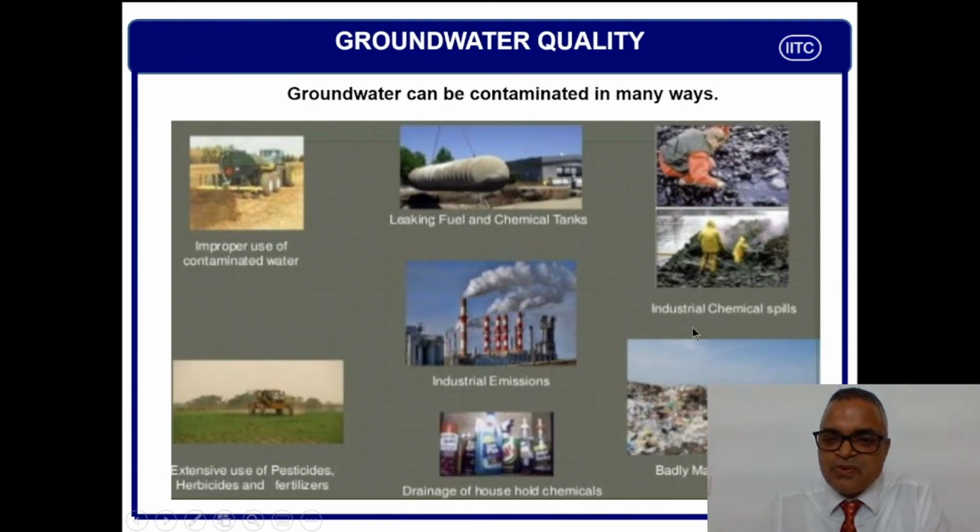My friend, be careful. Badly managed landfill. You see, we see bigger and bigger heaps in the landfill. We feel this is very good, very safe. But guys, these are very poorly managed landfills. Probably it does not have an impervious layer. All the toxic water leachate will go inside the ground. It will go in the aquifer. It will contaminate the aquifer. Ultimately, we are extracting the aquifer water. Ultimately, this is going to come back to us. Right, guys? Everything we give to our Mother Earth, she will smartly and patiently give back to us.